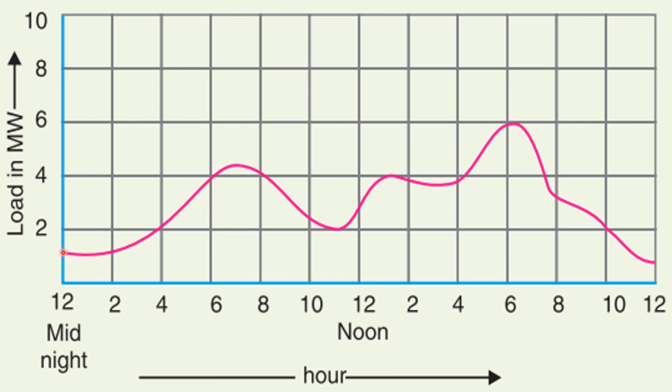So the value which occurs at 12 a.m. is sampled, and then it is held up to 1 a.m., and then the sampling is done again, and the new value is held up to 2 a.m., and so on. You can form rectangular sections of this curve by sample and hold, and then you can approximate the total kilowatt hour or megawatt hour energy consumption.